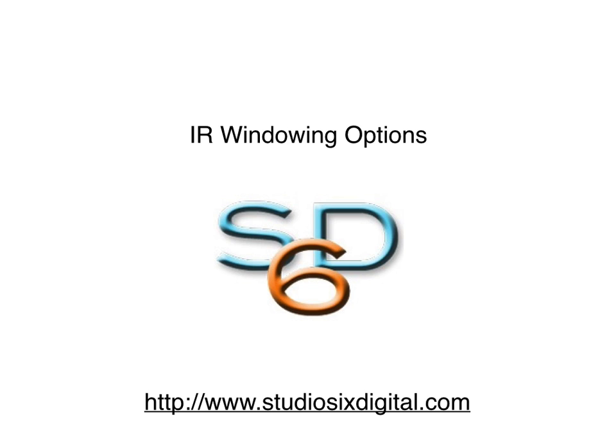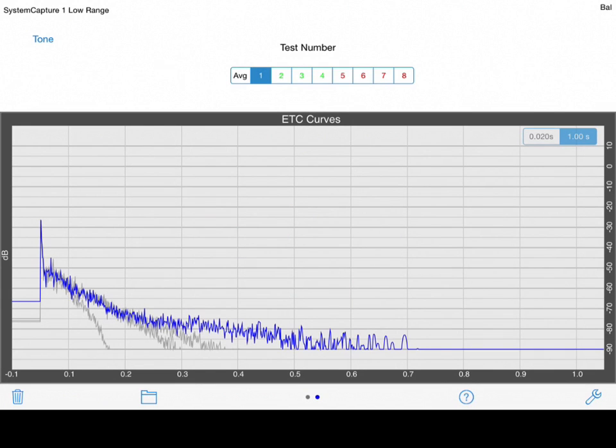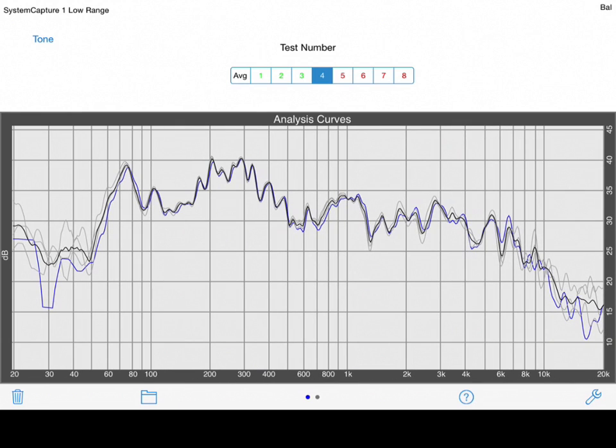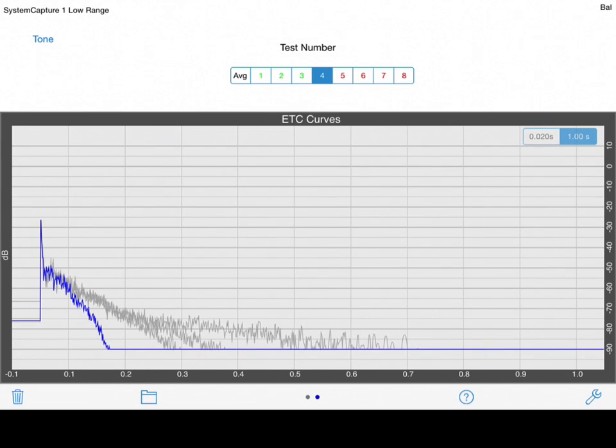After an IR is recorded, it is windowed in the time domain to reduce errors in the frequency response due to the abrupt stopping and starting of the IR sound file. Windowing smoothly removes some of the beginning and the end of the IR. Since most loudspeaker systems are being measured in rooms with relatively short reverberation times, this has minimal impact on the resulting ETC analysis.